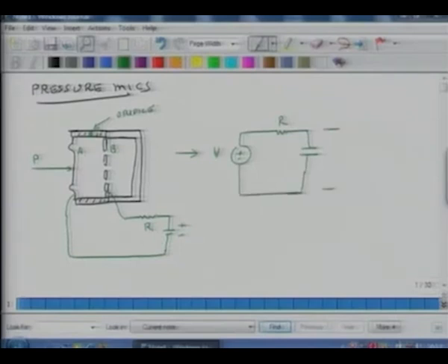And what I measure is basically this parameter V0, which is the voltage across these two plates. Actually, more often I measure the charge, Q. So these two plates are separated by some nominal distance. Let's say this distance is D. So my capacitance is C equals area of the surface times permittivity constant over the distance D, right?